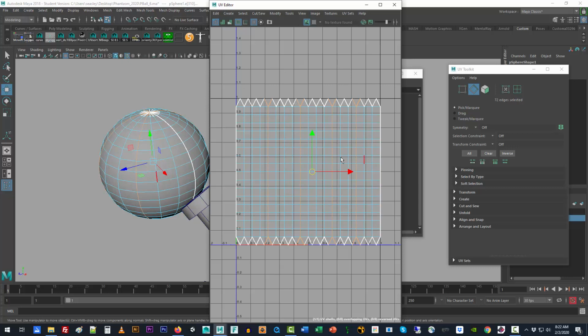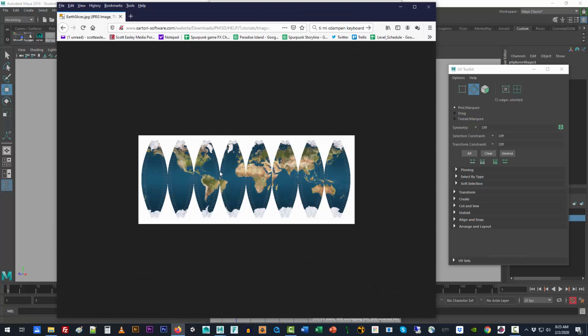Now what relax means is you're asking it to sort of lay out the UV sets as per the constraints of how it's built as a model. So in this case, when you ask Maya to relax it, it's going to relax these edges to pinch, very much like they are here in the model. So it will relax along the cut edges, so we have to cut these first, so that, like this example, we'd have to cut these edges.